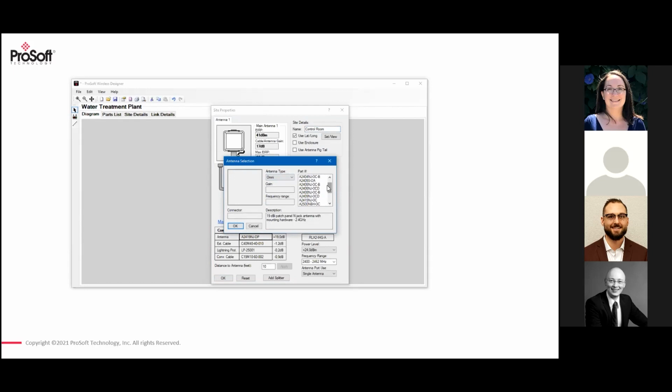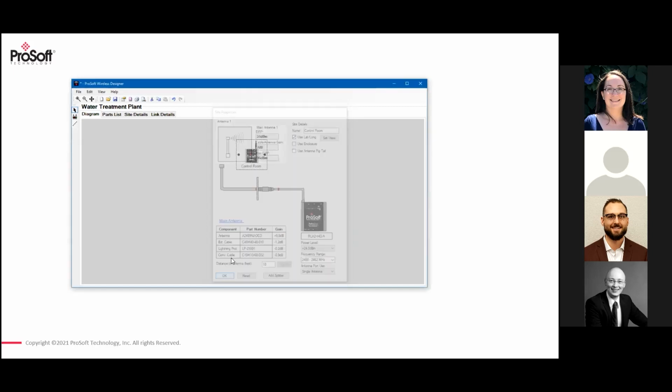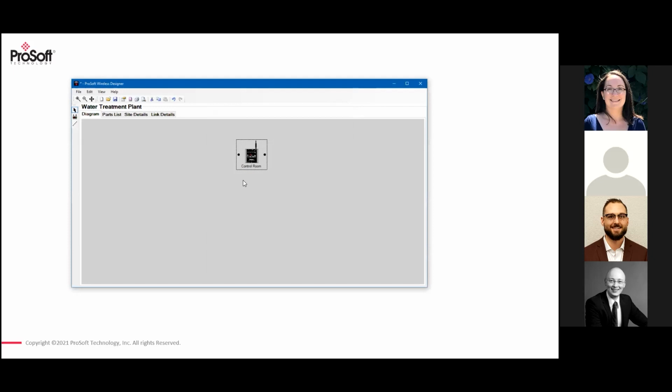So I'm just going to pick one of the antennas here. A stands for antenna. 2.4 means 2.4 gigahertz, which is the frequency we use, and I would recommend it for simple outdoor installations. And then the 09 is basically a 9 dBi antenna, meaning this is how strongly the antenna amplifies the signal. 9 dBi is a good mixture between sending the data everywhere and focusing it too much for just a simple point-to-point connection. And that was the most difficult part of the setup.